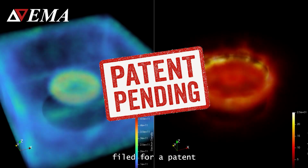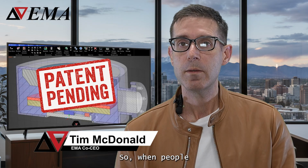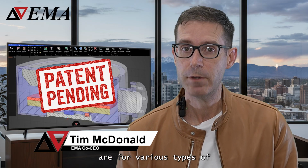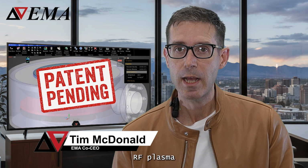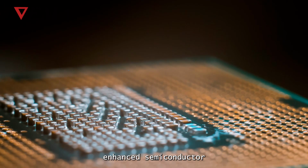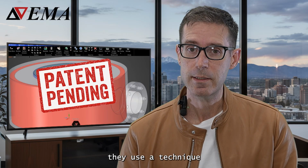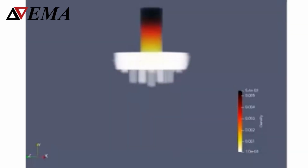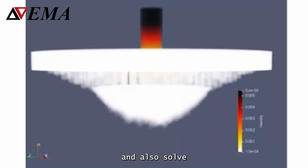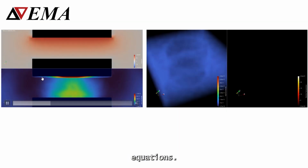So EMA has filed for a patent for our plasma simulation technology. When people do simulation of plasmas, the types of plasmas are for various types of RF plasma interactions. For example, in plasma-enhanced semiconductor manufacturing technologies, they use a technique called particle in cell to model electrons, ions, and other carriers, and also solve the electromagnetic equations as well as the Navier-Stokes equations.